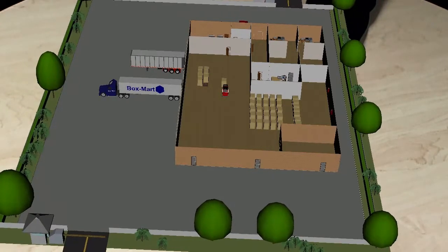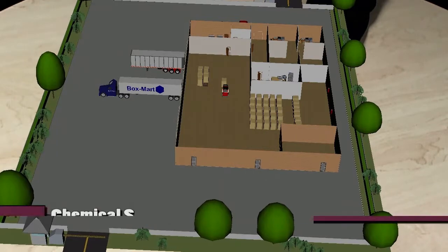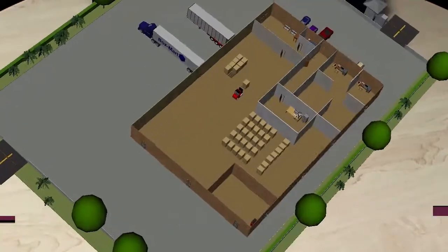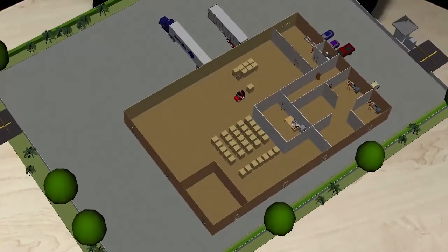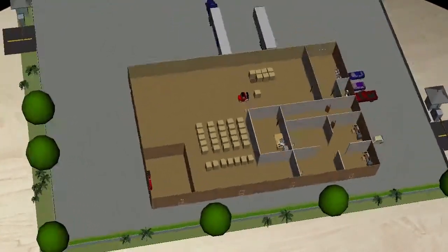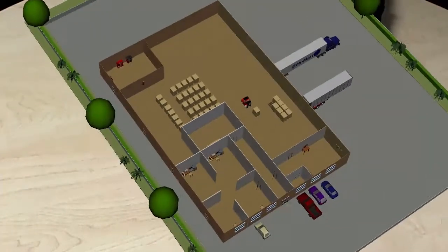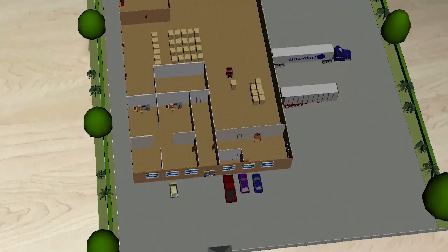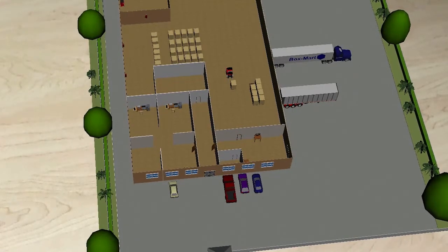So all of that has to be evaluated. Chemical storage, similar to product storage, is mainly going to be involved in the maintenance area, or possibly even, as you go back up to the front of the building, looking in housekeeping closets that may be present. So chemical storage needs to be done in a way that it's properly covered by sprinkler systems if it's flammable material. If it needs to be used by employees who are properly trained, it needs to be secured.